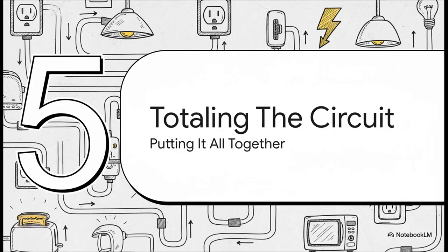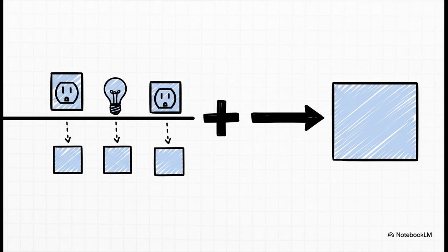Okay, our toolbox is officially full. We've got the rules for specific appliances, for all kinds of lighting, and for general receptacles. We know how to assign a VA value to pretty much any outlet you can think of. So now, it's time for the final most important step, putting all those tools to work. And the final step, honestly, is the easiest part. You just go down the line, outlet by outlet on a single branch circuit, apply the right rule from 220.14 to each one, and then you just add them all up. That final sum is your total calculated load for that circuit.